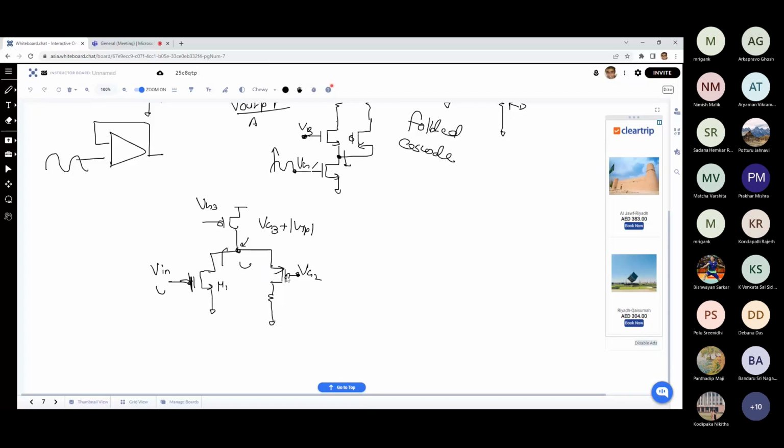And second is, here also I need to make sure that this transistor is not getting into cutoff. So the lower side, again, the constraint will be coming from the VG2 first, because here you have a higher requirement for the VG2. So you should not be pushing this into the triode region. So from a swing point of view, we should see how the maximum and minimum allowed voltage levels at the input and output nodes are changing.